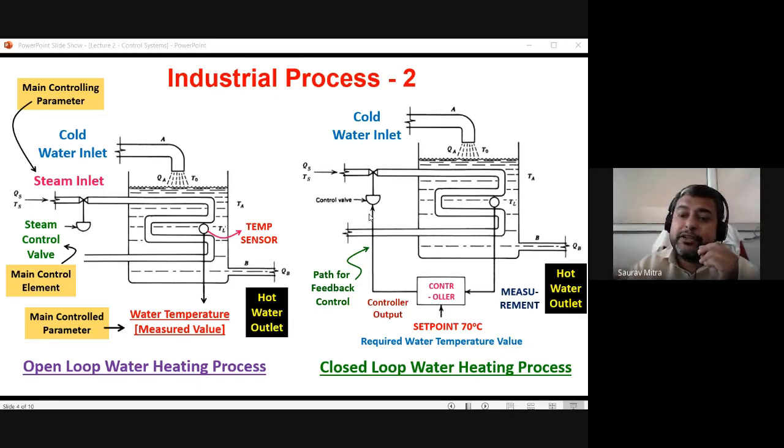We have set 22 degrees, that is nothing but the set point, and continuously there is a temperature sensor sensing the room temperature. So the room temperature is 30, then cooling occurs to 28, then 26. Continuously the comparison happens between the set point of 22 degrees and the room temperature of 30, 28, 26, 24. As soon as the room temperature comes to 22 degrees, the controller tells the compressor inside the AC that okay, the room temperature has now become 22 degrees centigrade, you take rest.